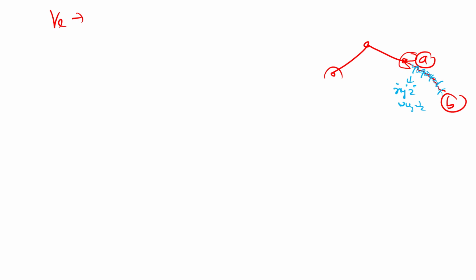So to find out this velocity, the user is in need of q dot. Q dot means joint velocity. When you give the joint velocity, automatically the manipulator takes up the end effector velocity. So for that, everyone should know Jacobian. If you know the Jacobian and we have the required end effector velocity, automatically we will find out the joint velocity.